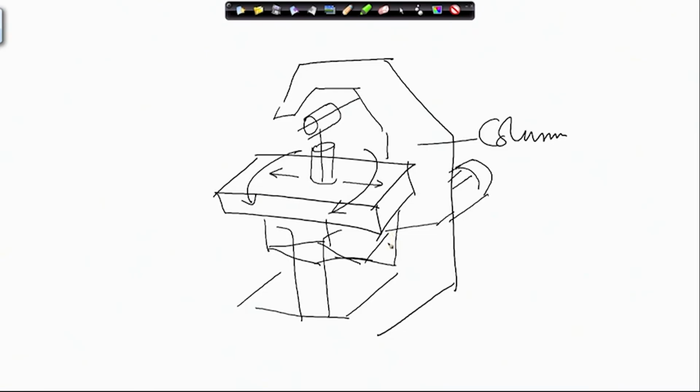And last of all, which I have not covered today, there might yet be another motor called rapid traverse motor, which can override. That means it will be deciding what the motion of the table will be, override the feed motions set and provide a faster motion to the table slides by a device called an overrunning clutch.